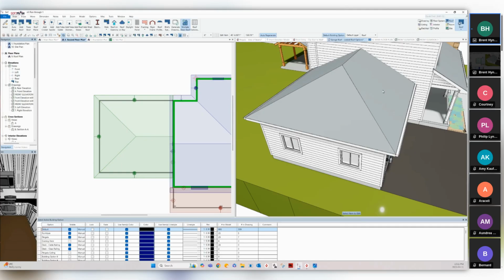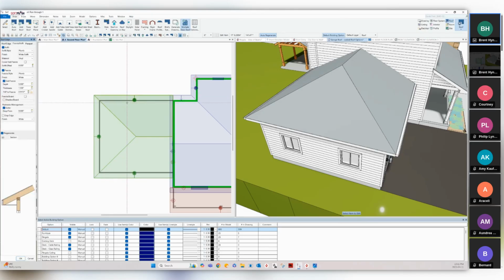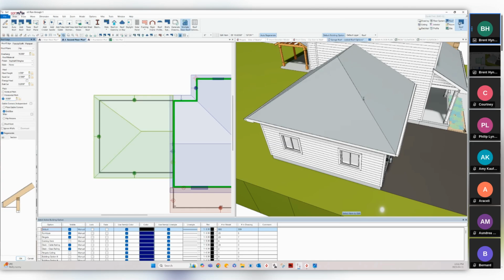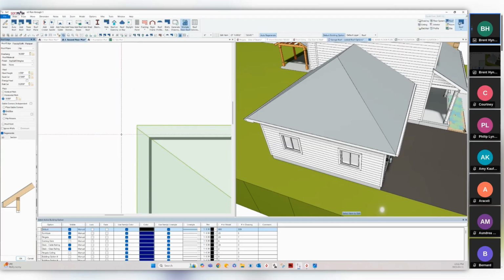And I'm just going to edit this one off. Say 8 inches. And you can see how that has now pushed it off of the corner. So if that's what you're looking for, just zoom that up for you. By holding one of those features, it's no longer going to keep the hip coming down on the corner. So all I was trying to illustrate for you.